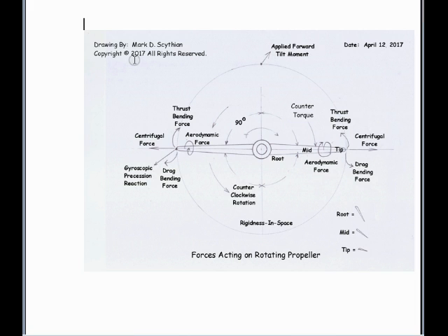So these are the forces and moments that are acting upon a propeller in whatever application, whether it's rotary wing for helicopters or propellers on airplanes. And then these are the forces, and then if you create another counter-rotating propeller, then all of these forces or moments applicable to precession and torque are also going to be canceled out, provided you can rotate these at equal and opposite RPM.